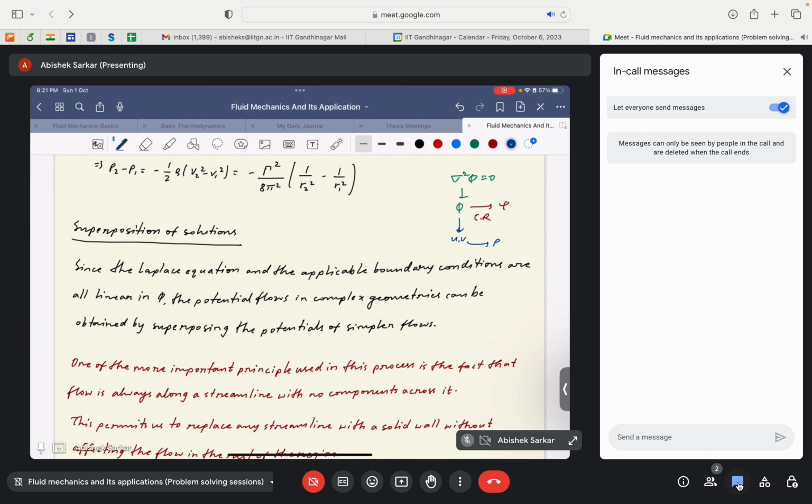Nowhere here are we having to deal with a non-linear equation. So you may ask, in the case of pressure, is the equation non-linear? For the first iteration that we are going to solve, we know U and V. That's why the equation is not non-linear, because we are just considering the advective terms to act as source terms, in the sense that the only unknown would be the pressure gradient term in that equation.